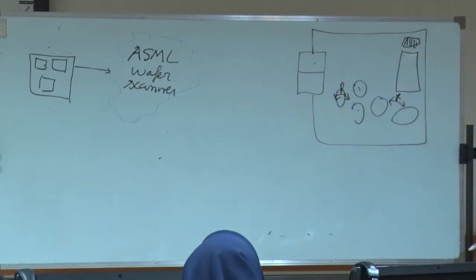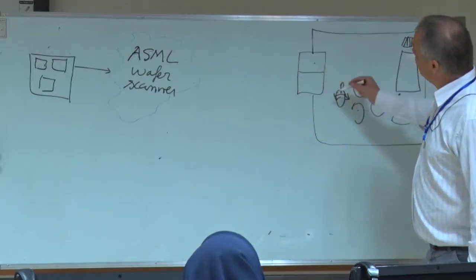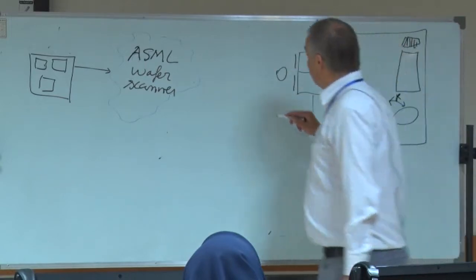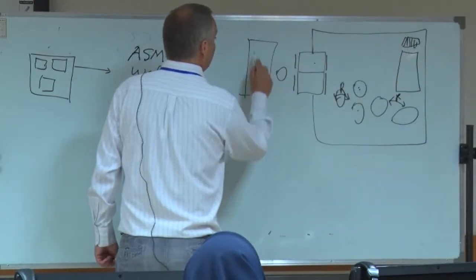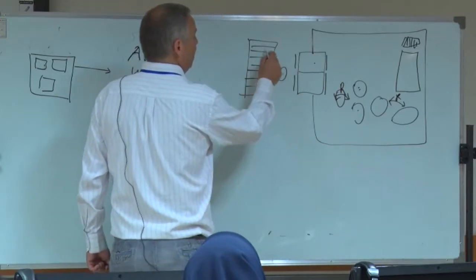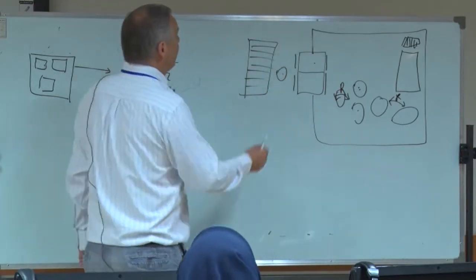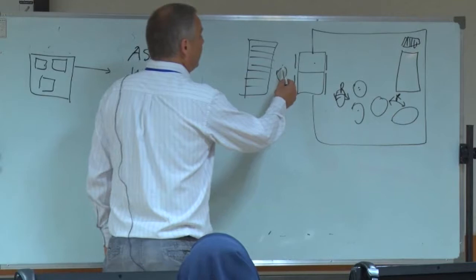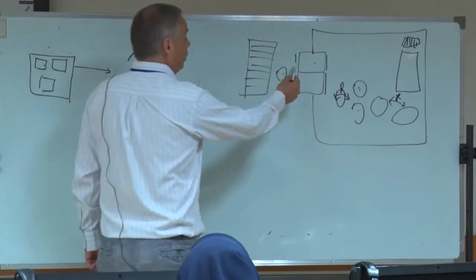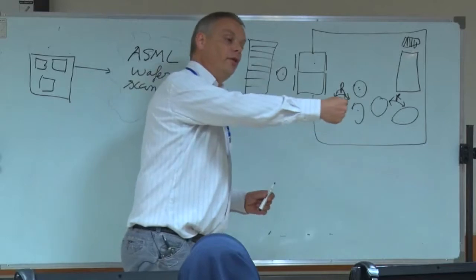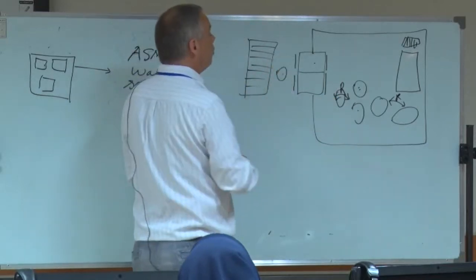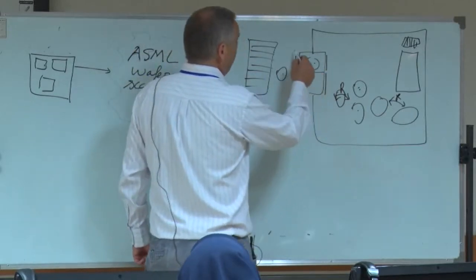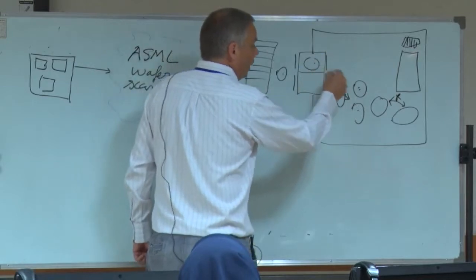You can use both sluices here. So here we have a door, there's a door, there's a door, there's a robot here, and there is a stack of wafers here, and this robot simply picks out a wafer. Then the door should be open, so your control system should first instruct the robot. Then, of course, we should take care that the door is open, otherwise it will bump into the door, which is not allowed. Then there is this position where you can put a wafer. Then you should close this door, open that door, and the wafer is moved in.